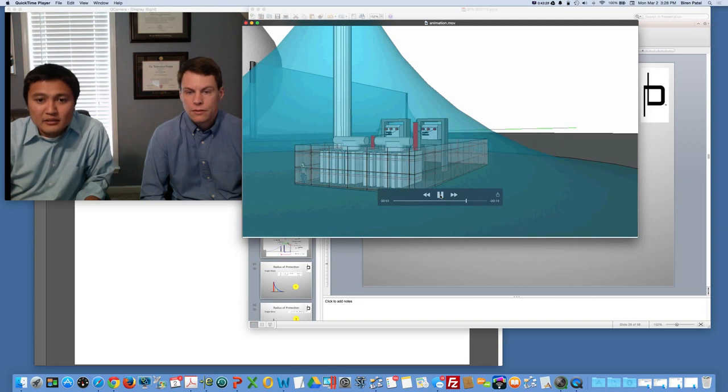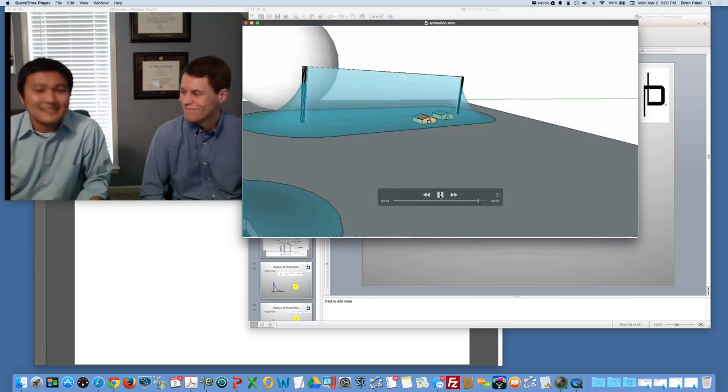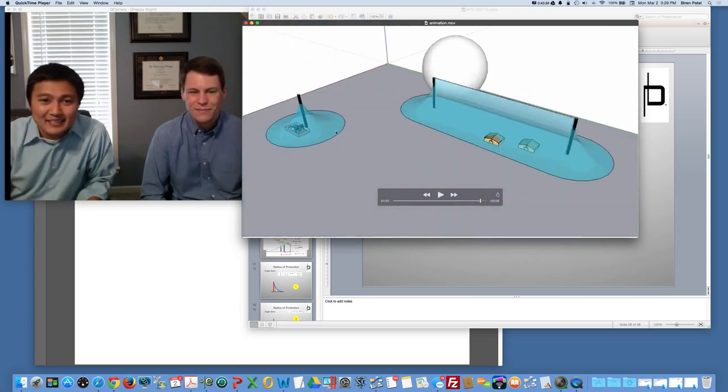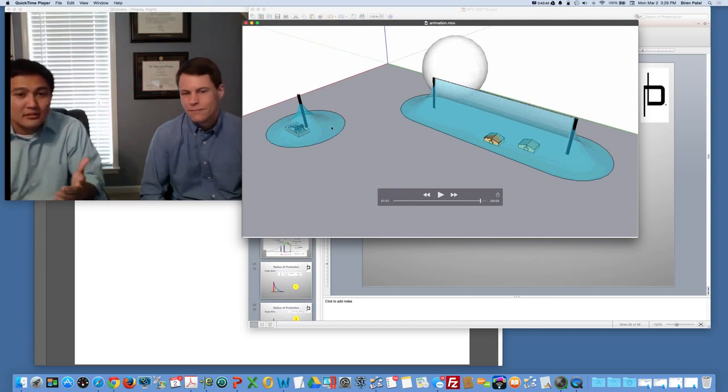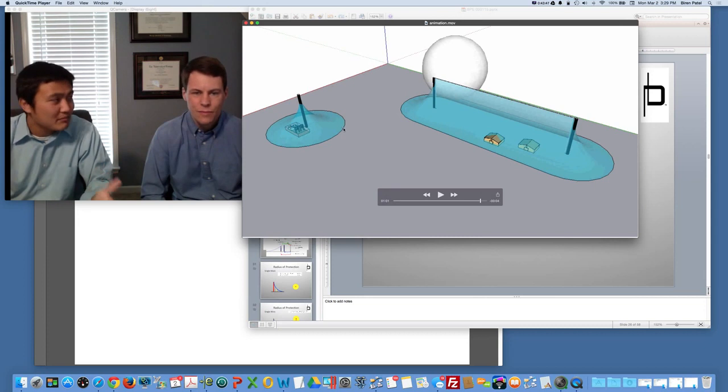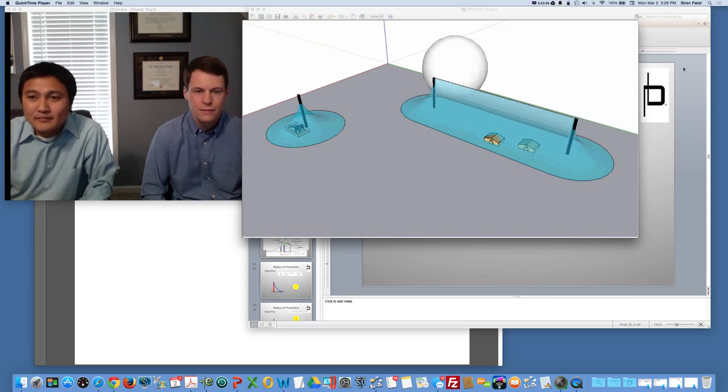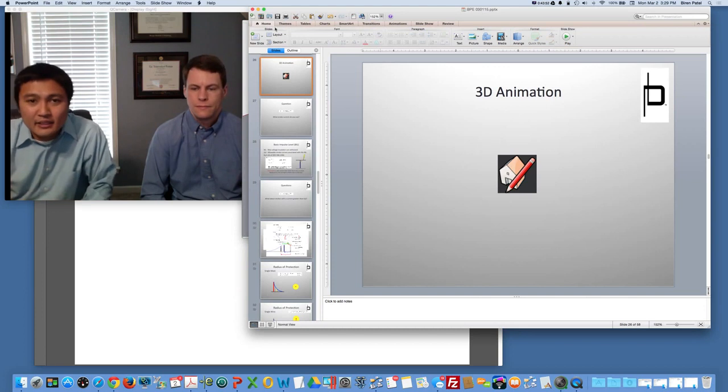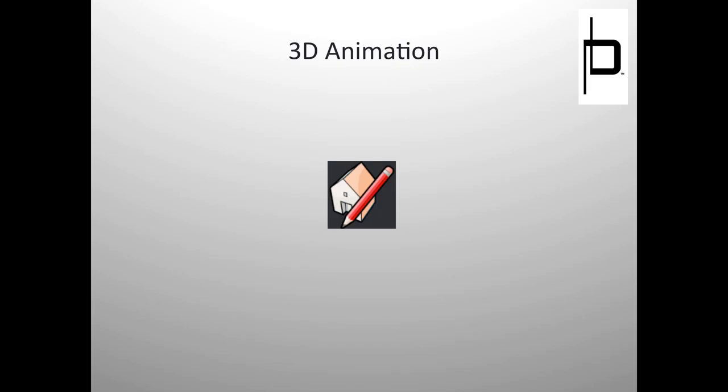And then this is showing us what a single mast would look like. I like to call this shape a witch's hat. It reminds me of a witch's hat. That's generally the shape that you would get, and you can see, like you mentioned earlier, it is very similar to the cone shape. So that should give you an idea of the kind of shapes you can generate, protection wise.